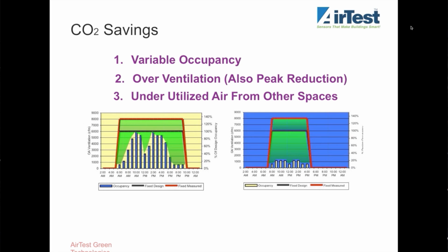The important thing to note when we're talking about outside air is that, if you think about heating and cooling a building, recirculated air, as it comes back, you're only cooling it or heating it a couple of degrees to bring it back into a rational level for the space. But outside air, as it comes in and goes through the air handler, the temperature difference, the humidity difference may be quite significant. And so generally the amount of energy that you're spending on conditioning outside air far eclipses that of just reconditioning recirculated air.